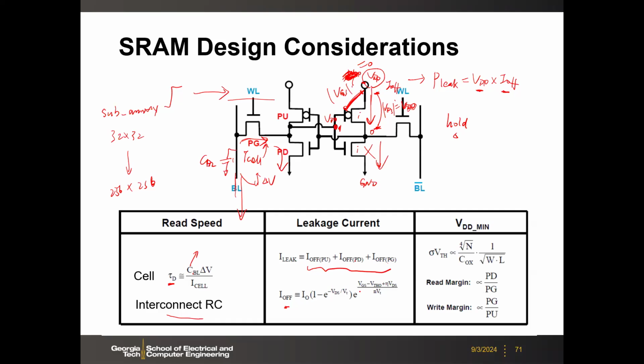Okay, so then the leakage power is a great concern for the SRAM. If you look at total power consumption, of course this depends on the activity ratio, right? If you are not very active and are in standby often, then the SRAM power consumption will be dominated by the leakage power.